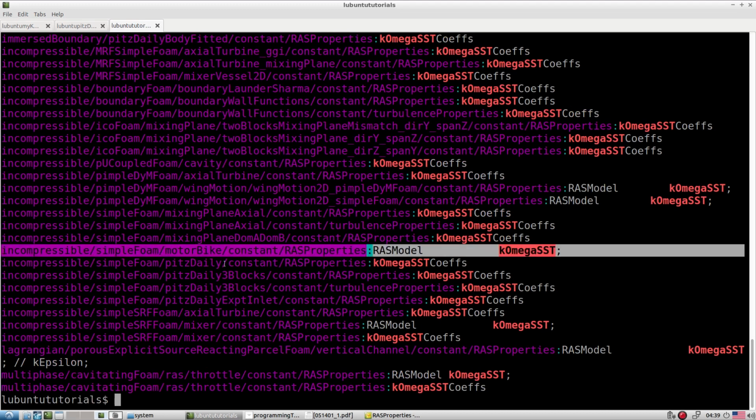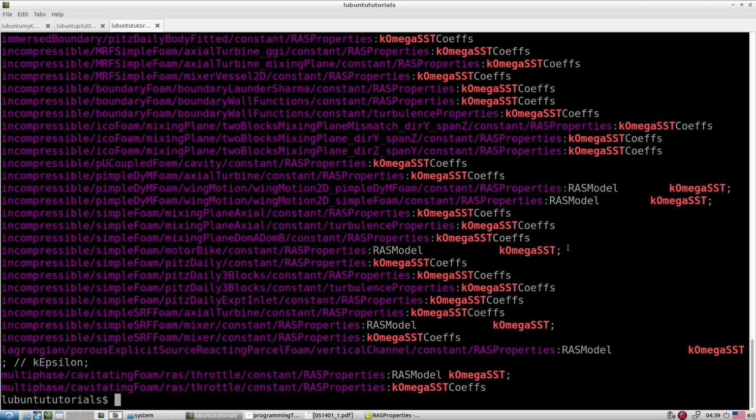So the incompressible motorbike test case we are using, so you can run our newly developed model on this incompressible motorbike model, and figure out whether we are getting a converged solution or not. A couple of tutorials are available inside the release version, so you can adapt that and straight away try to compile.